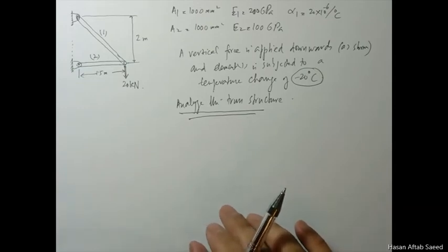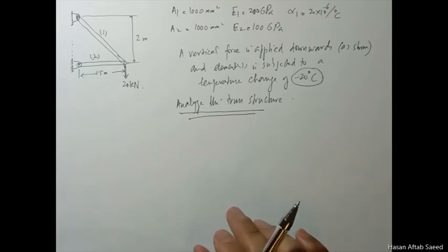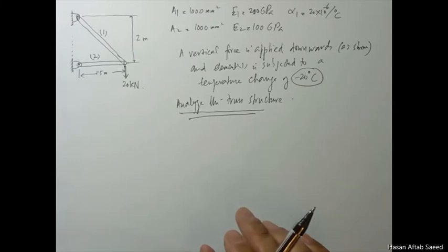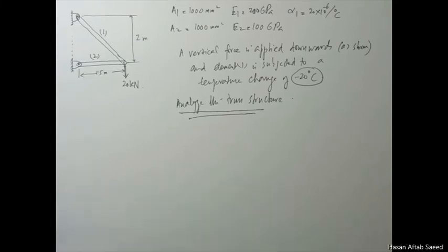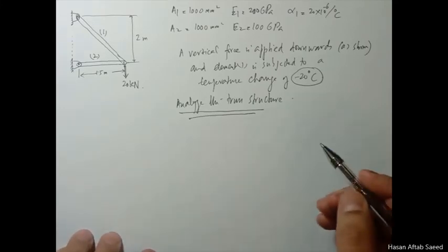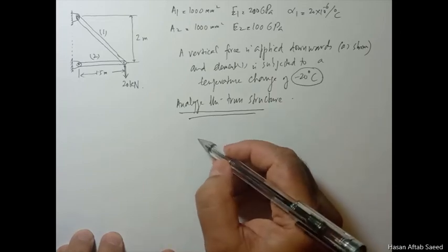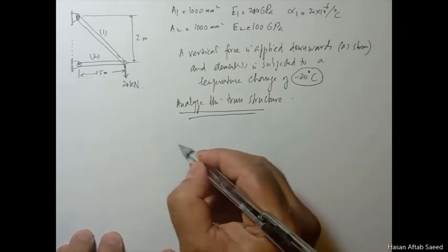But then before going to stresses you will subtract the thermal strain from the strains to get the mechanical strains, and then use the Young's modulus to find the stresses. I'll just give you the solution, the answer for it, and leave the students to do it yourself.